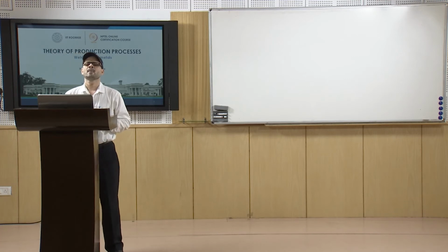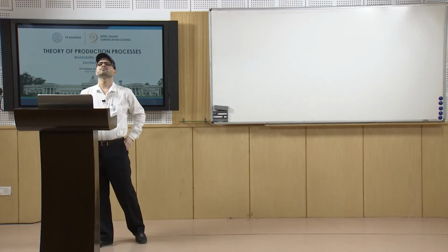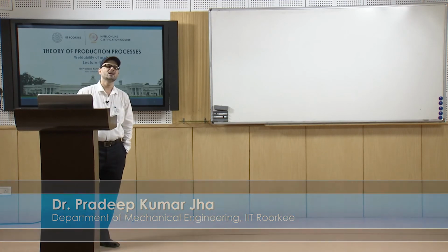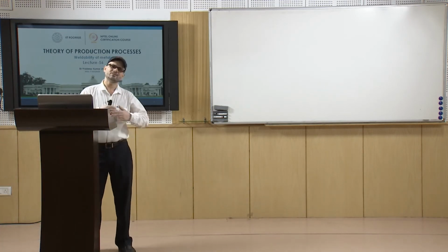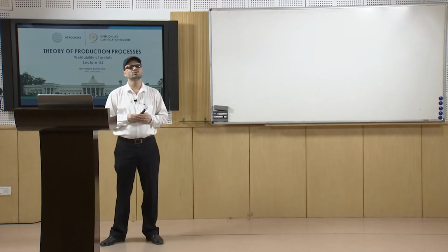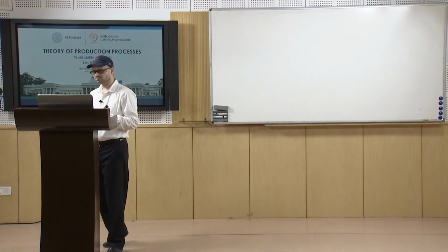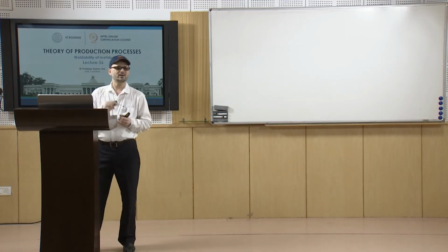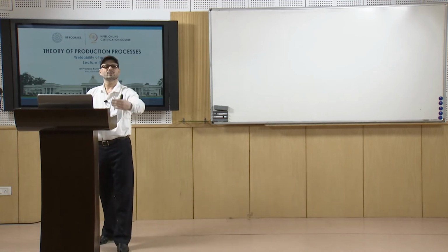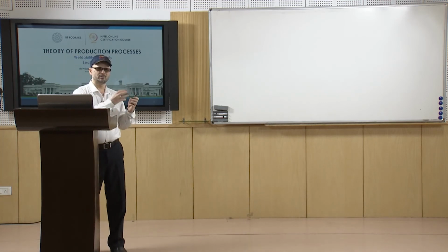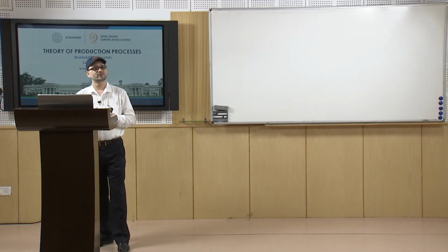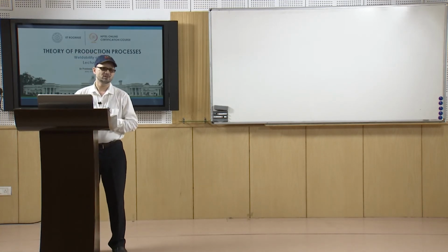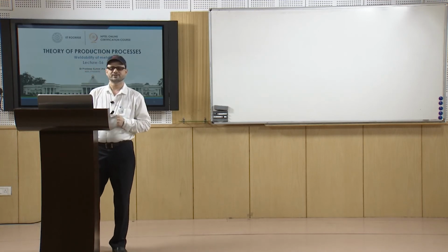Similarly, the alloying elements also take part in the formation of age hardening precipitates. Mostly in the case of non-ferrous materials, if you have alloying elements, age hardening takes place once you do the welding. After welding, because the cooling rate is quite fast, the age hardening precipitates may form. The alloying elements will be making these precipitates, and they will be modifying the property of the region where the precipitates are formed. So, this is another role of the alloying element.